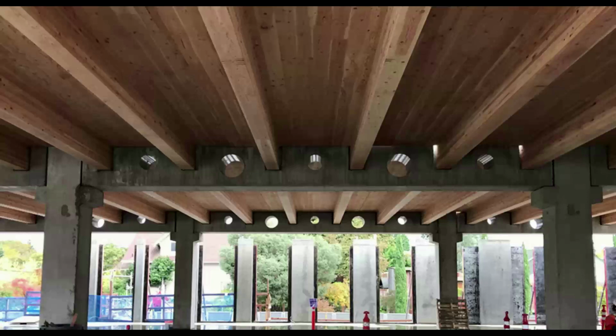Each floor plate was about 25,000 feet, and the contractor was able to utilize precast concrete columns and girders, and then wood double Ts in order to lay out that entire floor plate in about 10 days. That included the concrete topping slab. So really, a high rate of construction, very precise, and these buildings go up very, very fast.